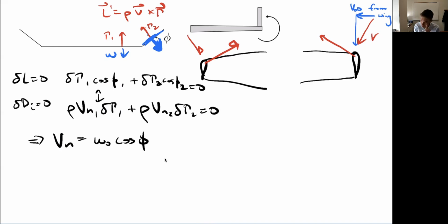But what I'd like is for the downwash of the winglet on itself to exactly cancel out. So actually, let's look at that first. Let's go back and think about a regular wing again. Easier to see on a regular wing, just planar. Here's our simple horseshoe vortex in the direction of gamma.